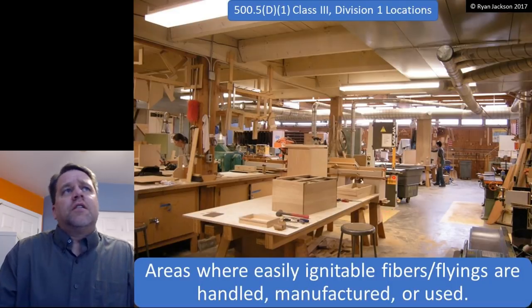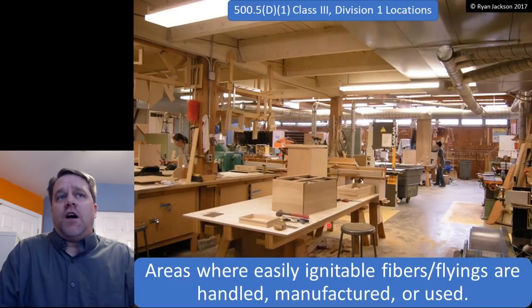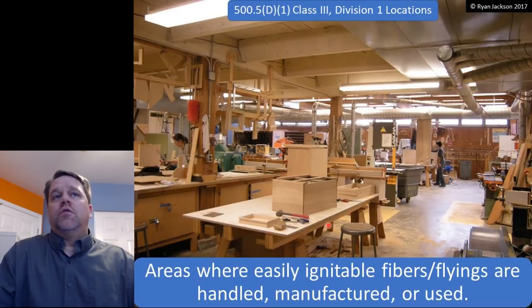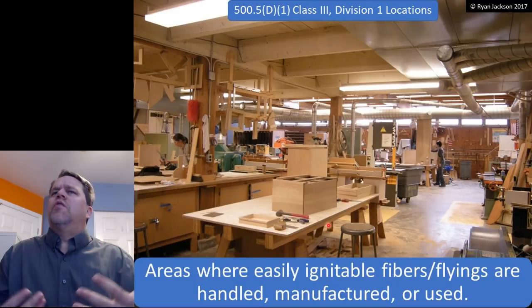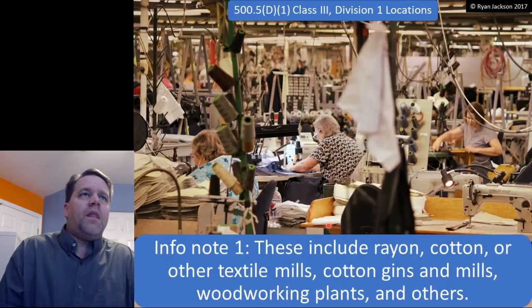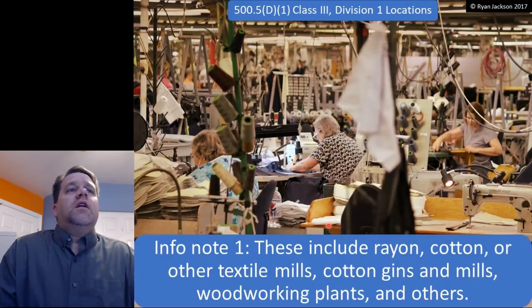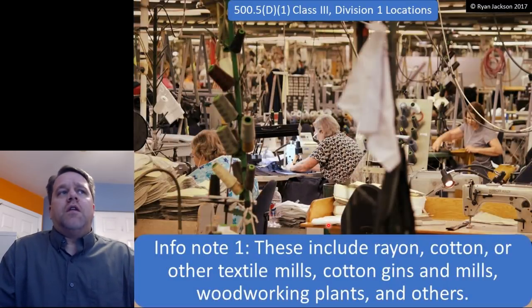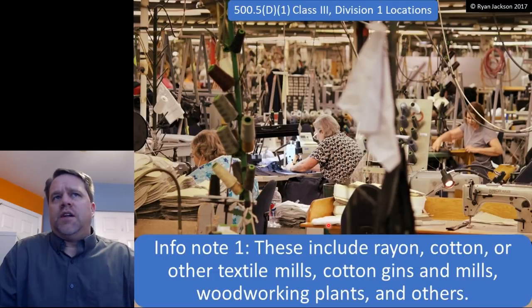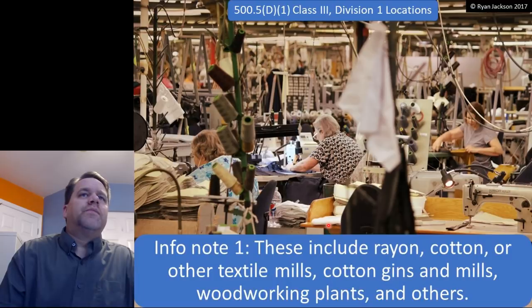So Class 3 Division 1 is an area where easily ignitable fibers or flyings are handled, manufactured, or used, basically where they're created. So this might be a Class 3 Division 1 location here in this photograph. There's an informational note. These can include rayon, cotton, or other textile mills, cotton gins and mills, woodworking plants, and similar facilities.